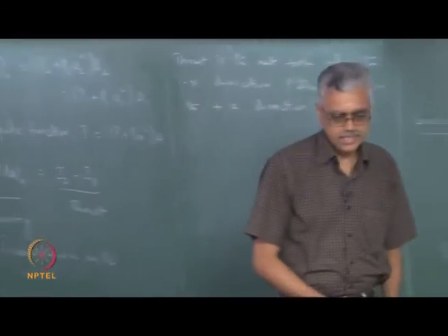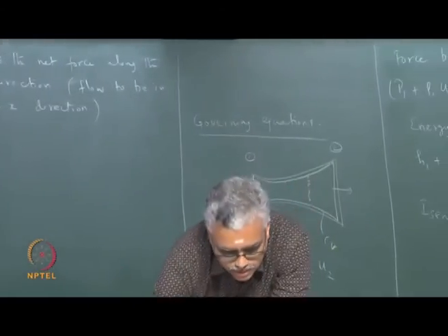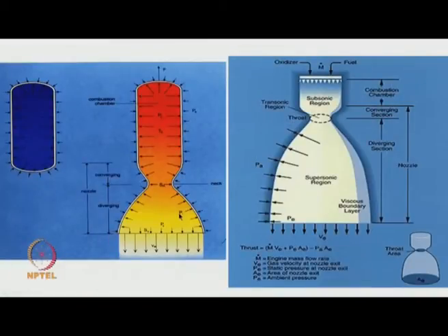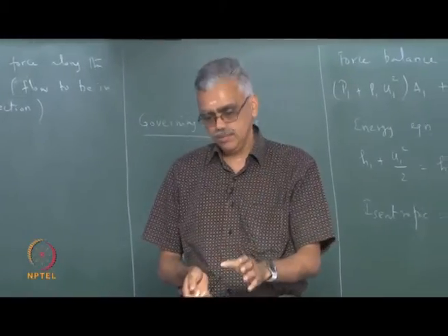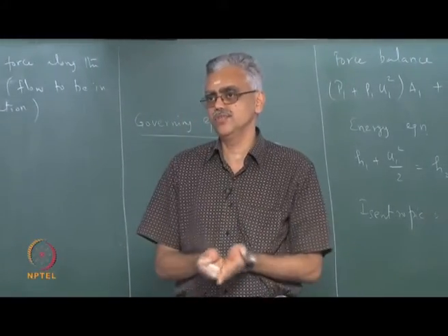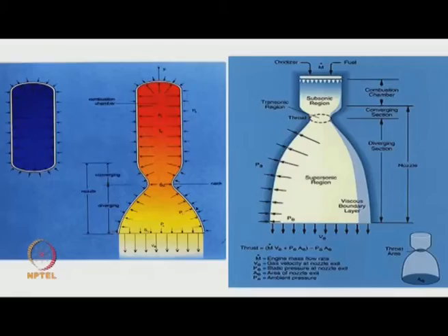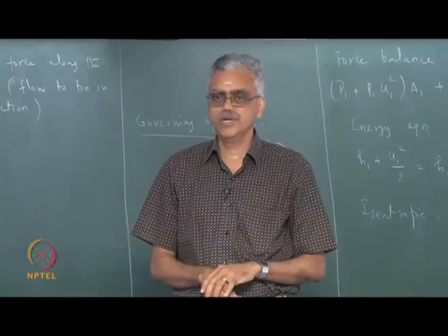So, you can see that the net unbalanced pressure forces produce thrust, as a result of which the vehicle or the airframe moves. I can calculate the force either by integrating the pressure force on the surfaces, evaluating the integral along each one of the surfaces and calculating the net force if it is possible, or I can calculate this as I2 minus I1.